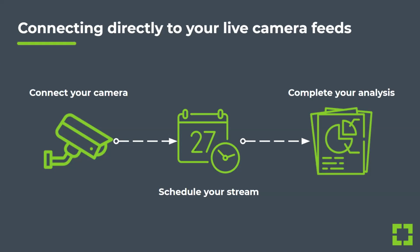Again, I will split it into 3 steps. The first one is that instead of uploading the video files, you will choose the connection to the live camera. And if your camera streams in RTSP already, you don't need to do anything on your camera. In GoodVision, you just enter the camera stream URL and the credentials if they're needed. After establishing the connection, you're ready to schedule your first traffic.